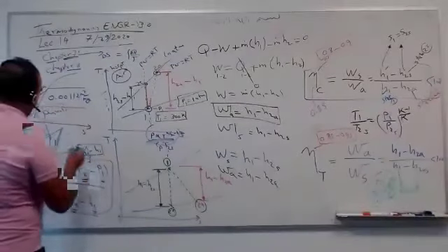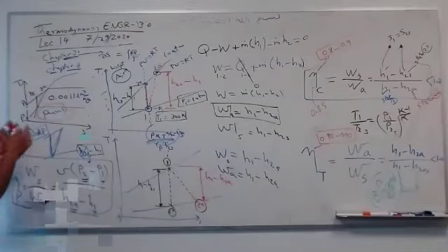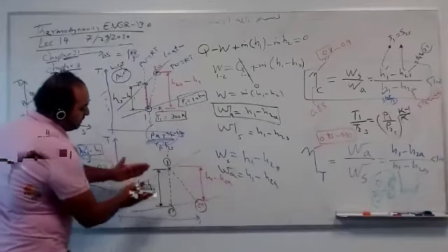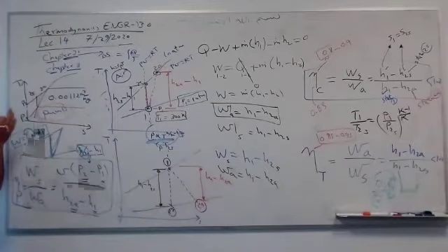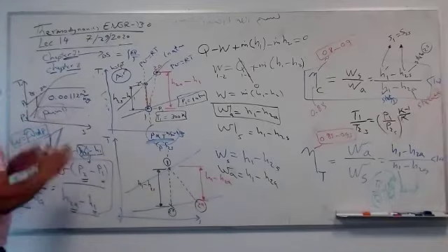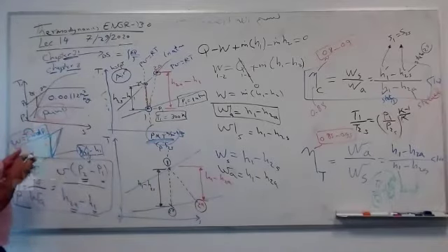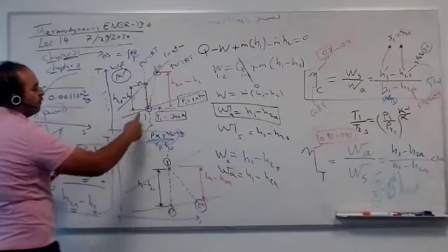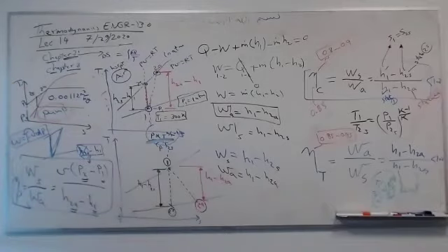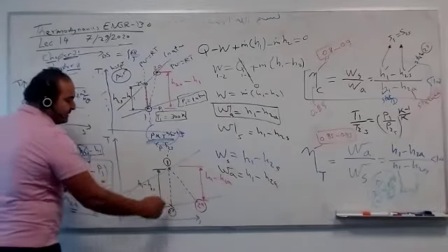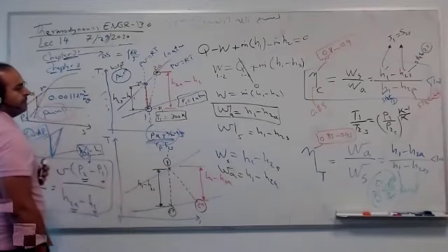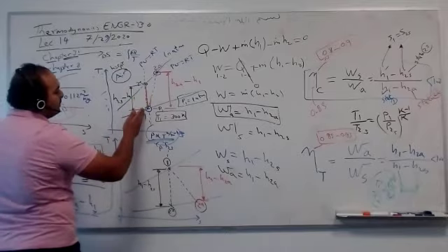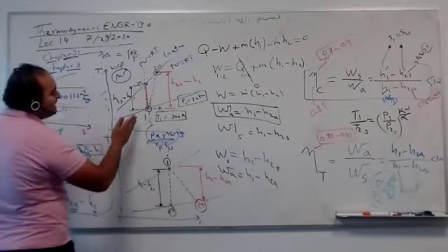For compressor, turbine, or pump, the whole idea is that the pressure lines are diverging, going away from each other. For a compressor, I'm adding pressure to the fluid. The fluid was at 1 atmosphere, going to 10 atmospheres. When I compress, I wish to go vertically, to pay less. When I expand, I wish to go vertically to get more. This is the definition of divergence. But in reality, I'm going slanted, with a slope, with delta S, with irreversibility.